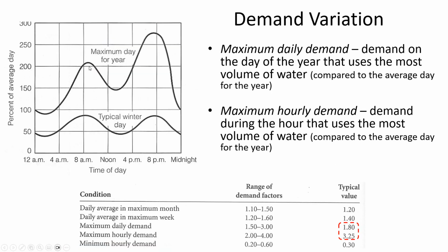Well, people don't use water at just a constant average through the entire day. Like right now, you're not using any water at all. You're just sitting in this room. But you probably use more water in the evening when you're showering, washing your clothes, flushing the toilet. And on a population average, they've studied this behavior and see how the water demand varies hour by hour.